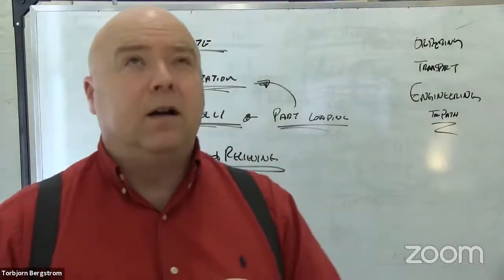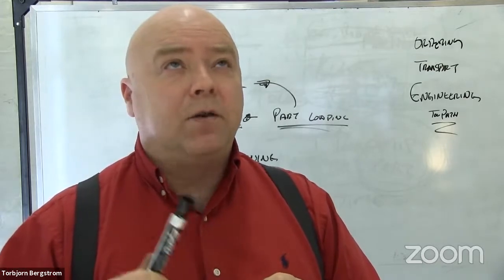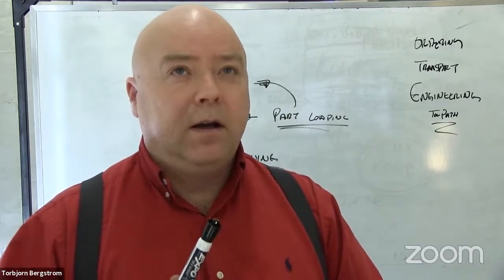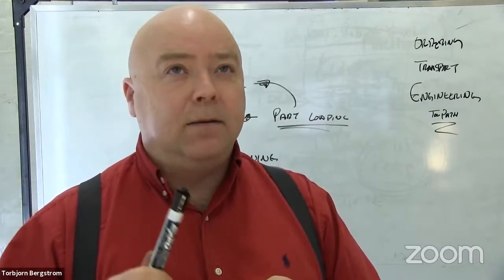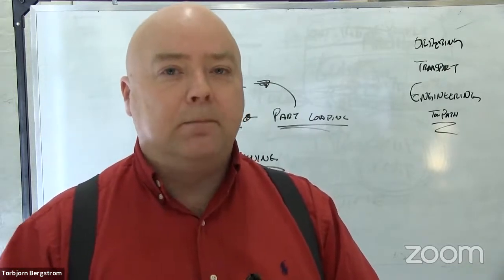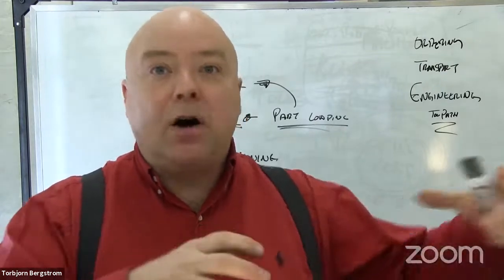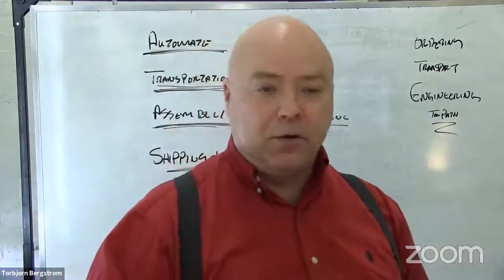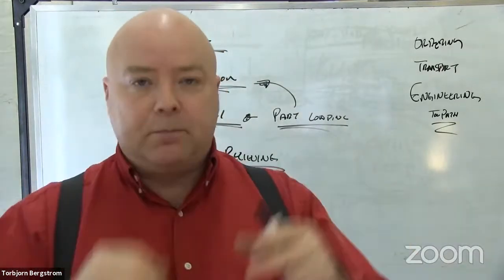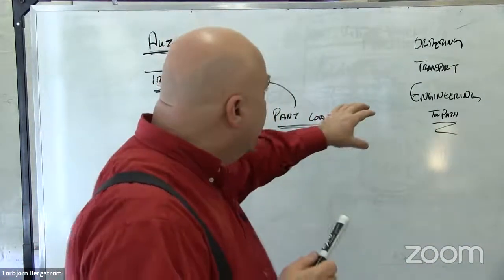I met a guy from a company. They have 3 software guys. They use Esprit and they generate 8 million code files a year for their CNC shop. Because they've used the automation that's built into the CAM software, when the part file comes in, they say, oh, it's this kind of part, and drag and drop it onto the box that makes code for that kind of part. So you can automate a lot of that engineering stuff.